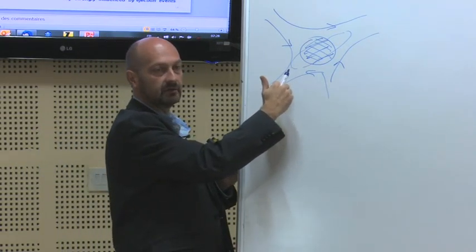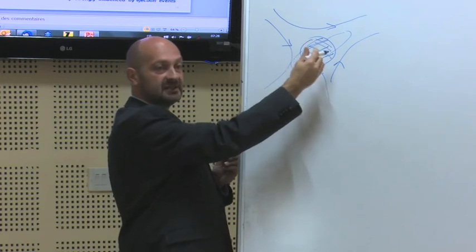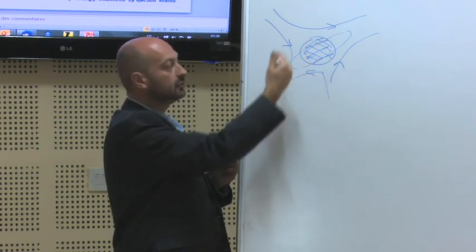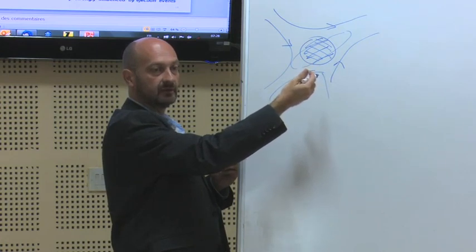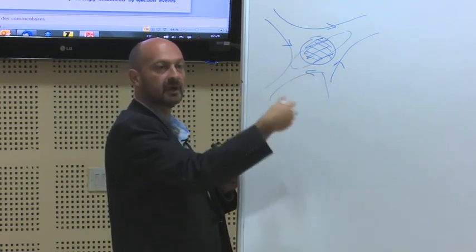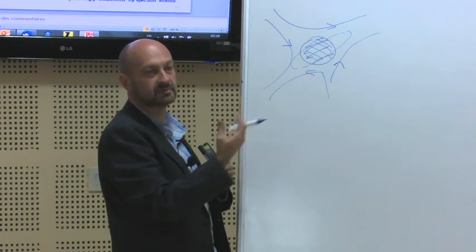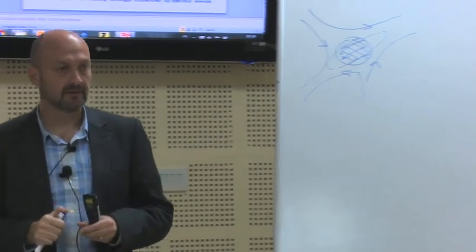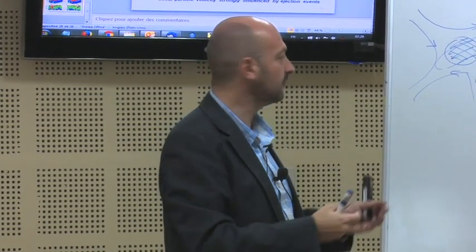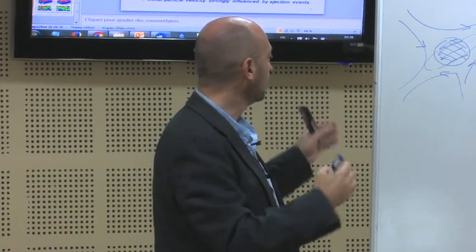But because it is a particle, it cannot deform. It is solid, so it will resist that forcing of the flow, and then it will generate some stress inside the liquid, and this stress is going to interact with the flow instabilities. So this is what we expect. If there is a gentle flow and then there is an obstruction, you can find some turbulence also. Yeah. Exactly. So this is what we expect. But for now, we are not sure what is the effect of the size. Because you may have different sizes, but this is the mechanism we expect.